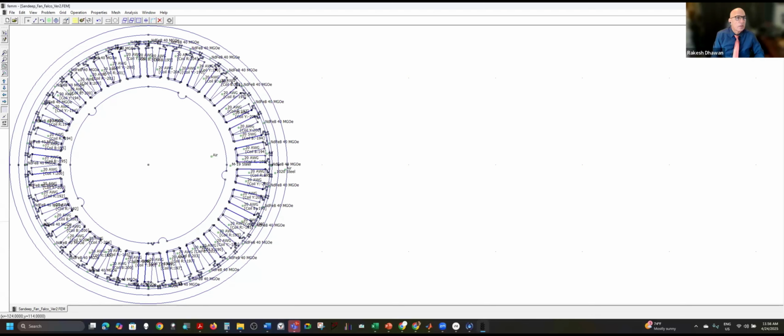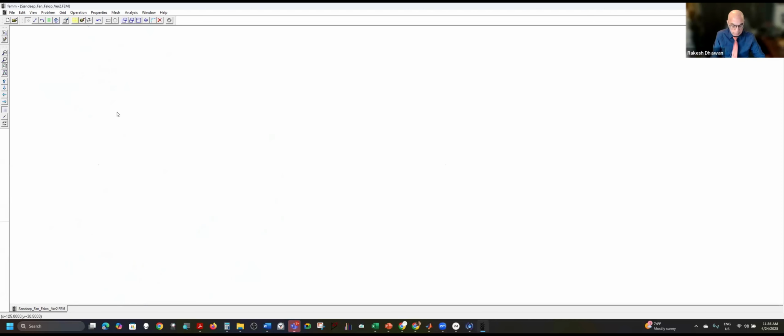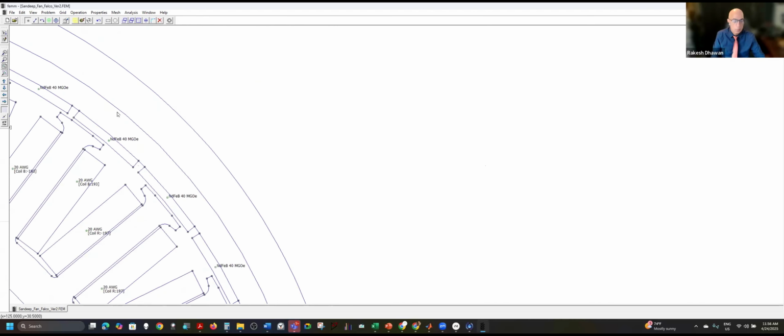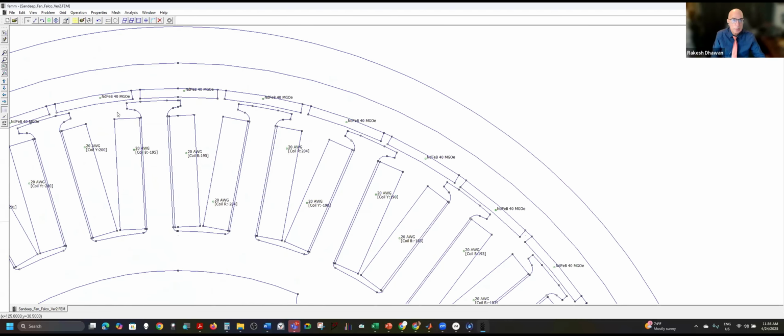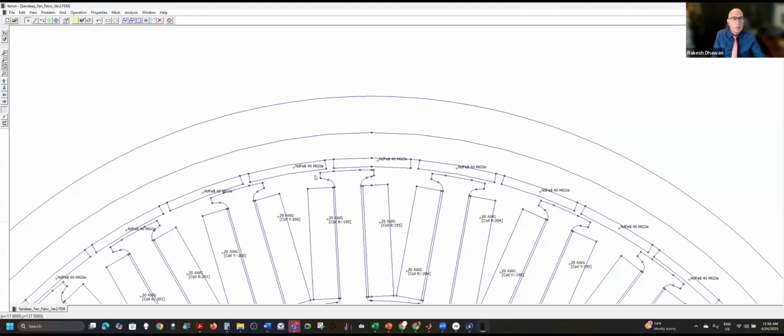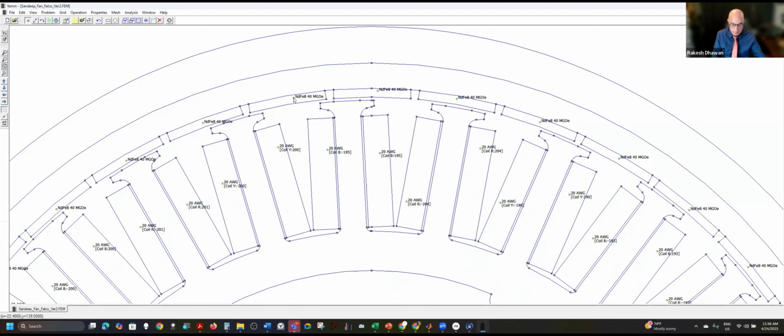Okay, and you can see here you can zoom in with page up, and you can see how you bring in a geometry. And here what we have done is align the parts, so I select this here and this point here, and I can hit space, and I can see it's a neodymium magnet. I have to give a magnetization direction. Here it is theta. I'll show you in a minute what theta is.